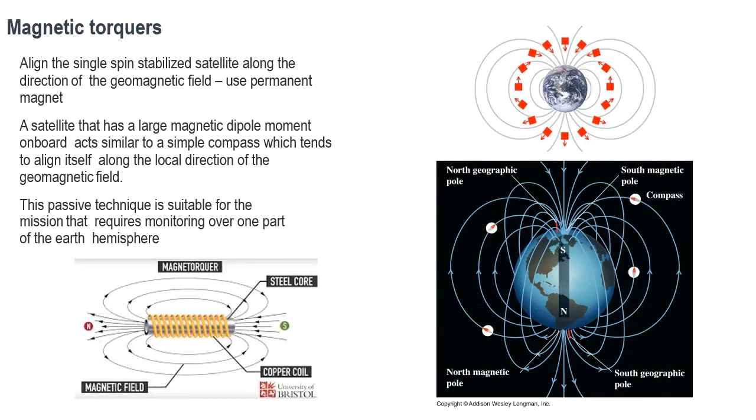A set of orthogonally aligned torque rods is wired up so they can generate a magnetic dipole field of either sign. They can generate a magnetic field of arbitrary orientation. This artificial field interacts with the Earth's magnetic field to produce a net external torque on the vehicle that will tend to line up the field. This torque only has 2 degrees of freedom. Instantaneously, the torque rod will tend to align the vehicle and the Earth field, with no control of rotation of the vehicle around its magnetic pole.